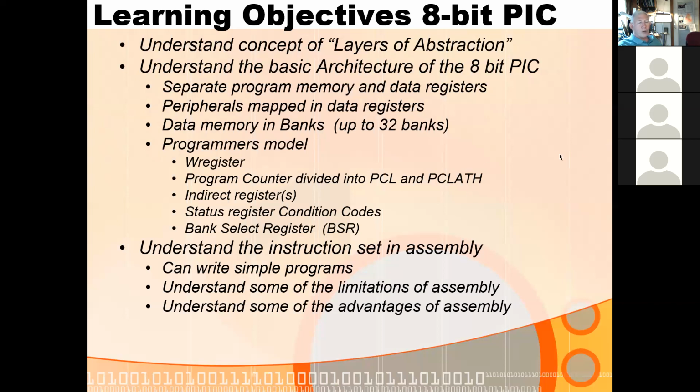This one is Harvard architecture. A lot of the microprocessors are von Neumann architecture. We'll talk about the differences there, but that doesn't really matter because there are plenty of other, even ARM core based processors that are Harvard, and some that are von Neumann. So learning one or the other is not really a big deal. If anything, learning the Harvard first sets you up to understand all of them because it's the one that's a little different, and the von Neumann is a little more straightforward.